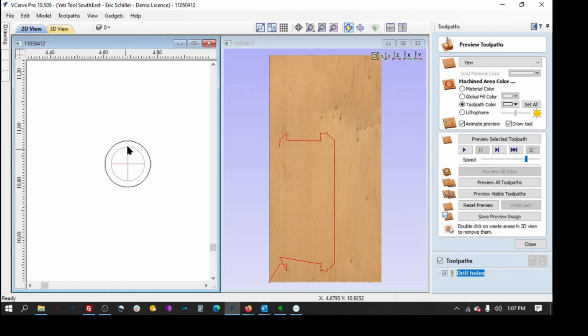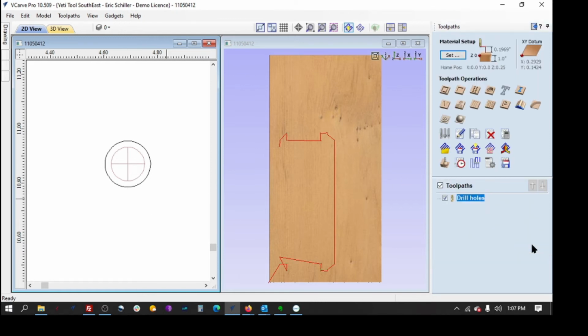I can also do this as a pocket where it comes in and it spirals down with a standard 1/8 inch bit, and we'll come to the edge of this vector of each of these holes and spiral down and cut it. It doesn't matter. We can handle it with standard tooling. They may already have a 0.13 bit already made. Doesn't matter how we get there. It's not a problem. So I've got that.